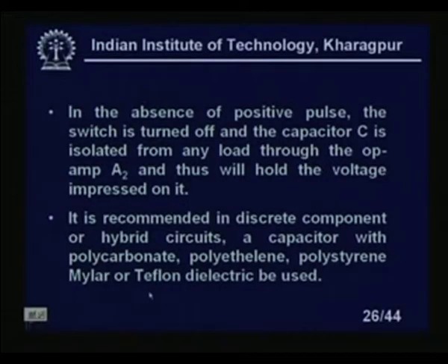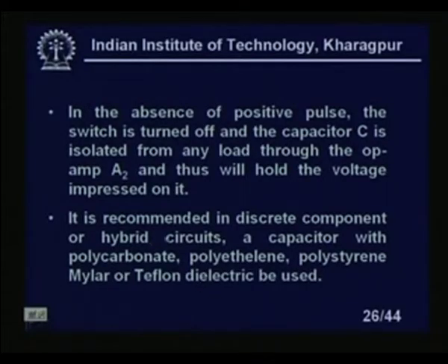We will discuss what are the different types of capacitors typically used for making sample and hold circuits. It is recommended in discrete component or hybrid circuits that a capacitor with polycarbonate, polyethylene, polystyrene, mylar or Teflon dielectrics be used, because all these names actually came from the typical dielectrics of the capacitors. This is the dielectric which is placed inside the plates of parallel plate capacitors. We are not necessarily talking of parallel plate; it can be foil type also, as happens in the case of electrolytic capacitors.